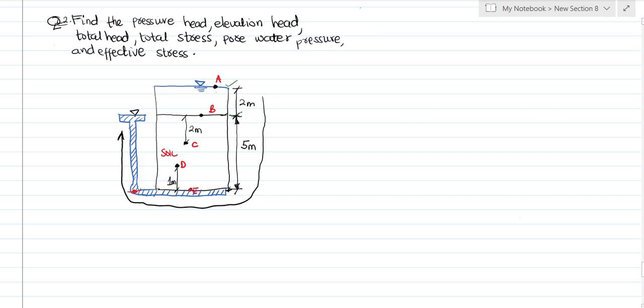The water head here and the water head here are two different heads. Do you get it? So this has a higher head, and this will be the direction of flow. The direction of flow is going to be in this direction. So with that in mind, let's see what the question asks, knowing the direction of flow is very important.